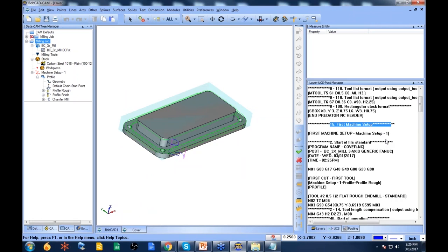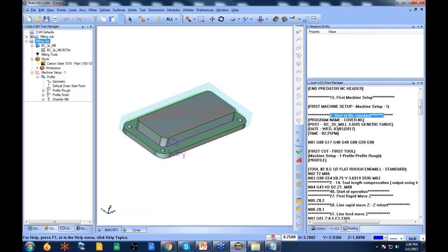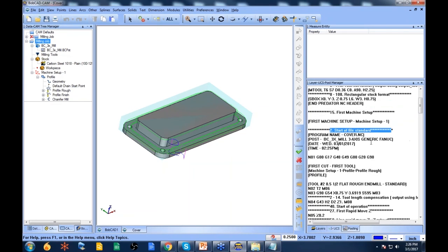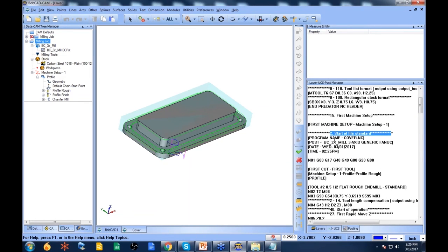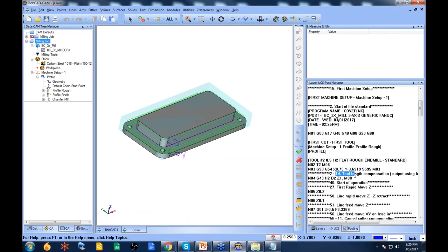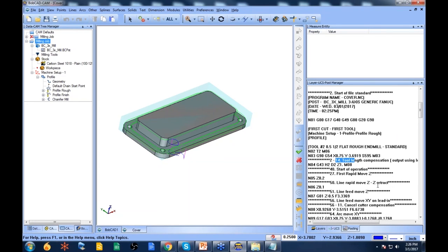The 29 does have a different post processor engine. We've made a bunch of improvements that make commenting out things easier than in the past. It is well documented. Within the BobCAD folder, there's a document under posting, there's documentation, PDF files, etc., so you can read about what all the variables are. But the first thing would be to put it in debug mode so you can see where the codes are coming from. The next thing is to learn how to edit the variables or hard code in what you want.